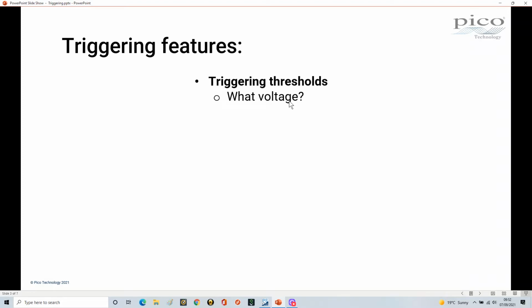And this is about analyzing and understanding signals. This is why I say about using oscilloscopes, it's important to understand what you're looking for in order to set oscilloscopes up. And yes, I know there are auto features. If you've been watching other videos, you know I'm not overly keen on auto features because they don't educate you and you're not in control of your test equipment.